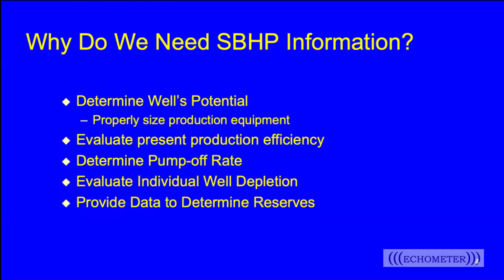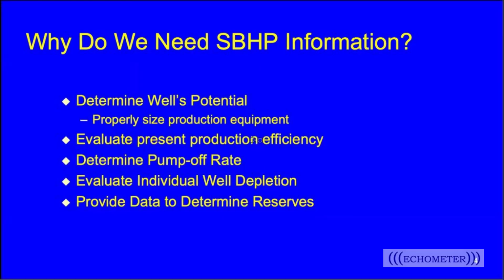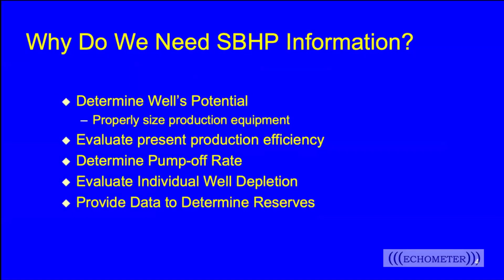But why do we need the static bottom hole pressure? Why do we want to take advantage of today's environment? Well, one of the things we're going to emphasize today is that we need the static bottom hole pressure information to determine the well's potential. If we really want to see how much production we can get out of this well, we need to do our inflow performance calculations, and the static bottom hole pressure is a key piece of information that goes into that.